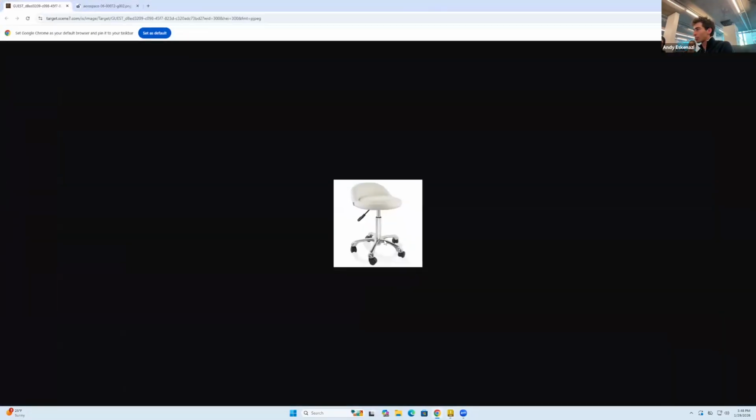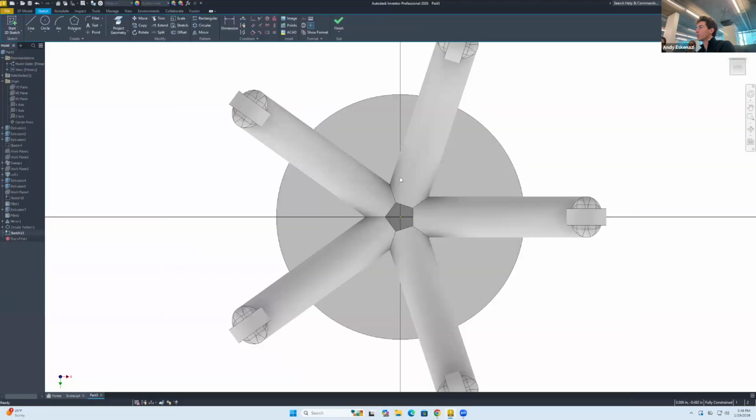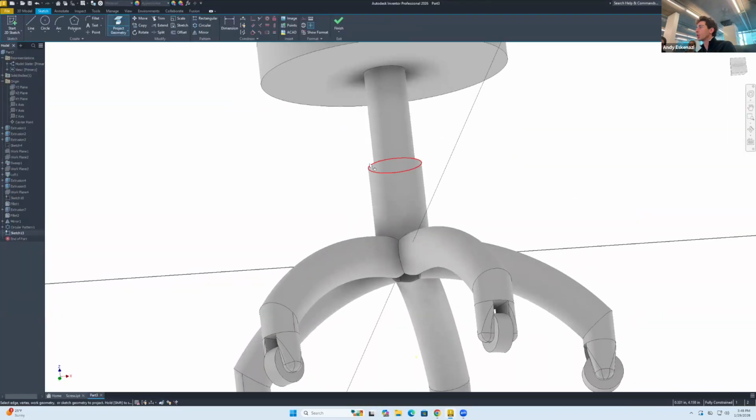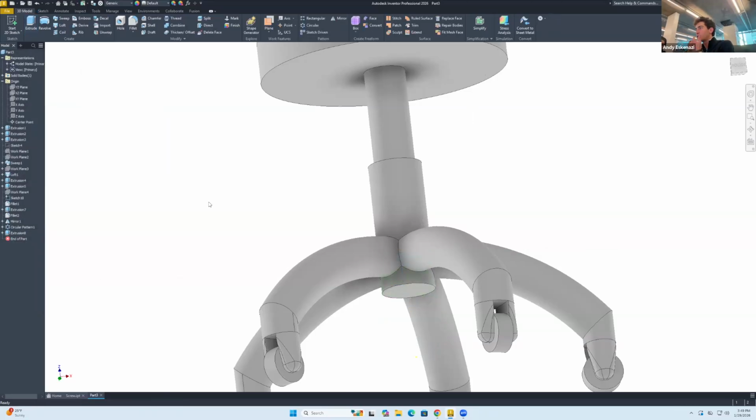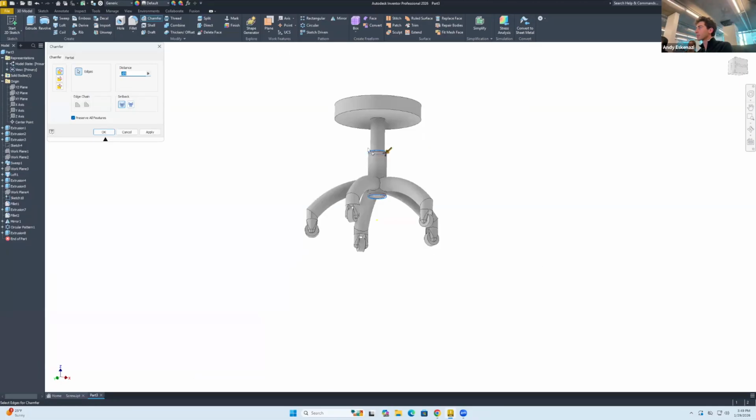But if you look at the picture of this thing, it has a little tube in there. So what we can do is project geometry that, and then we can go here to 3D model and extrude that by 0.1. Okay, let's beautify this thing. What do I mean by that? Adding a bunch of chamfers all around this place. 0.05. Just like that. And then we're going to add a chamfer here, another chamfer there.